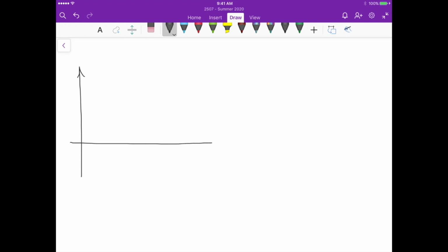So we have here the magnitude. So this is the magnitude. And for the Bode plot, we use the dB. So remember to take the magnitude, the linear, and then take the log 10 of that and multiply by 20, okay? So we have 20 here, 40 here, and 50 there. So 50, 40, 20, 0, and I'll put here minus 20, okay?